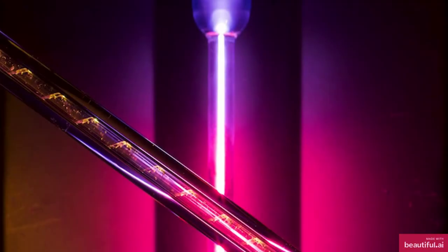Then, in 1990, ASML decreased the wavelength of light by using deep ultraviolet excimer lasers. Now, excimer lasers combine an inert noble gas, such as krypton, with a highly reactive element, such as fluorine, and at high temperatures, these elements bond to form krypton fluoride, and it's in a very excited state, so the molecule releases its excess energy in the form of ultraviolet light with a wavelength of 248 nanometers. So that shrunk the critical dimension of the chip further to 150 nanometers.